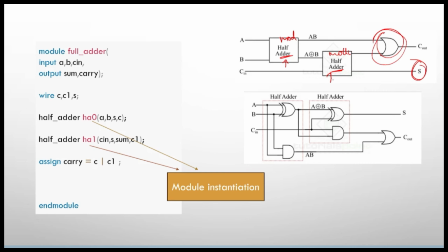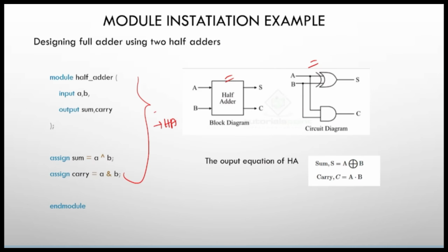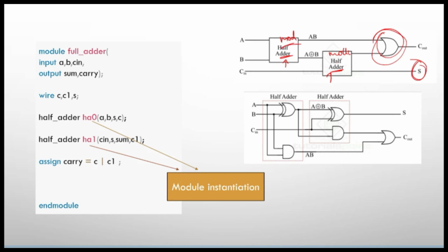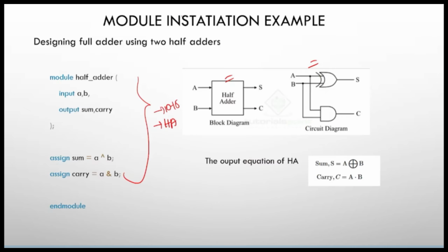If you see the code here, it consists of some 10 to 15 lines of code for the half adder. Now if you are writing the full adder by using the same 2 half adders, you need some 30 to 40 lines of code. Is it or not? While simulating your code, the lengthier your code is, the more simulation time it takes. So in order to reduce the time, memory and everything, in Verilog you have a concept called instantiation.